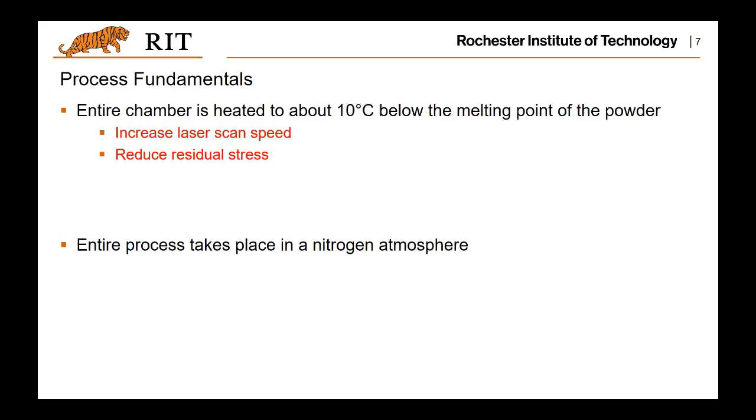Also, if the temperature in the whole chamber is raised to this level, the residual stress for the built part will be reduced, because the shrinkage of the plastic will be minimized by reducing the temperature difference between the environment and the built part. So that's the reason why we need to heat up the whole chamber.